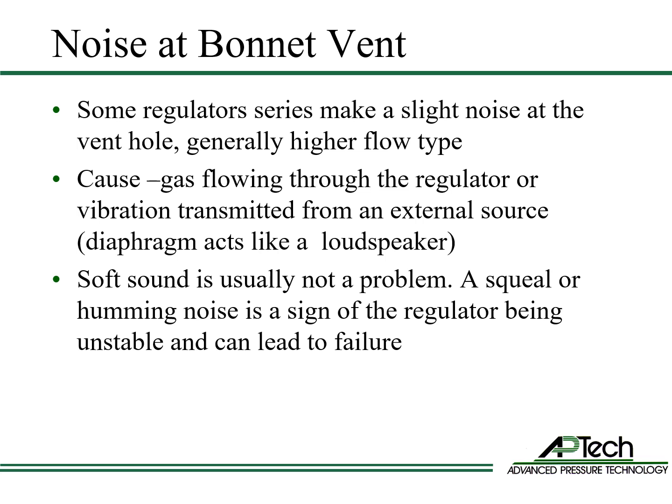Some regulators will have a noise coming from the bonnet vent hole, usually higher flow regulators. The cause is gas flowing through the regulator, or it can be caused by an external source of vibration. In either case, the diaphragm acts as a loudspeaker.